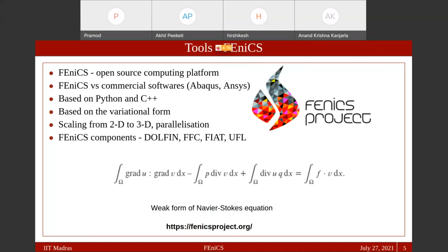Yeah, we can actually convert .inp to a readable file. But we need to use some other tools, meshio. Meshio is the way we can do that. But we have faced some issues. It is not that easy, but of course we can do that. We are going to show you a very simple way, GUI Gmsh, where we can get our meshing done. But I'm not sure about other platforms like HyperMesh. I know we can convert our .inp to a readable file in FEniCS.